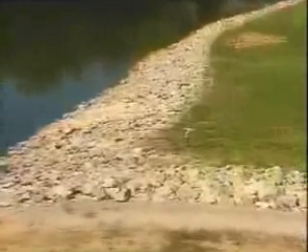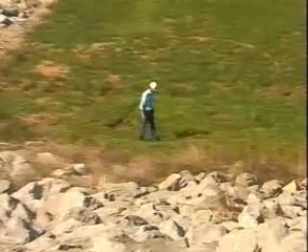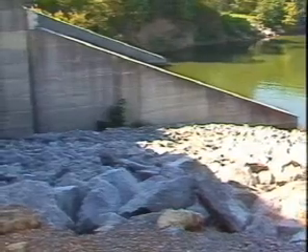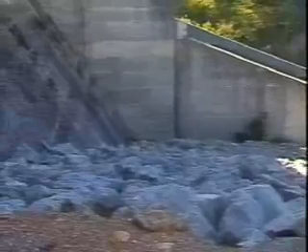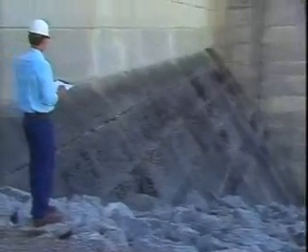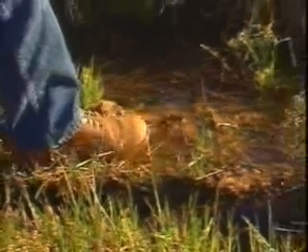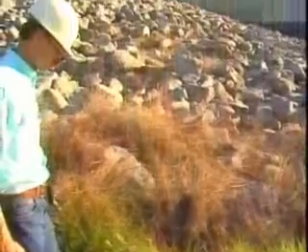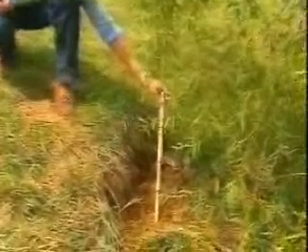When inspecting the area downstream from the toe, look for deficiencies such as seepage and depressions. Examining the abutments is also an important part of inspecting a concrete dam. Cracking, scarps, and bulges may indicate instability in the abutments. Also look for seepage or signs of seepage, such as lush vegetation. Or sinkholes.